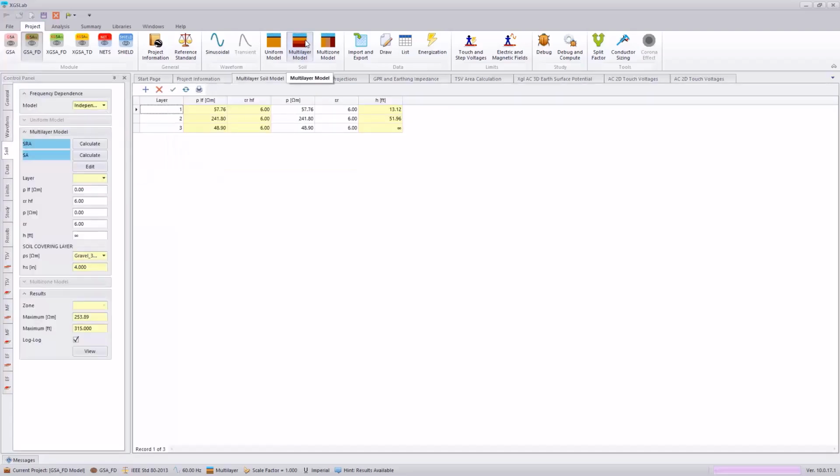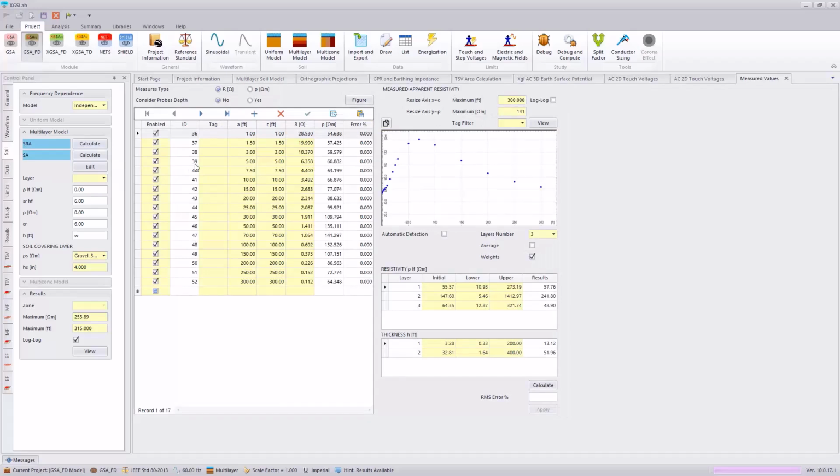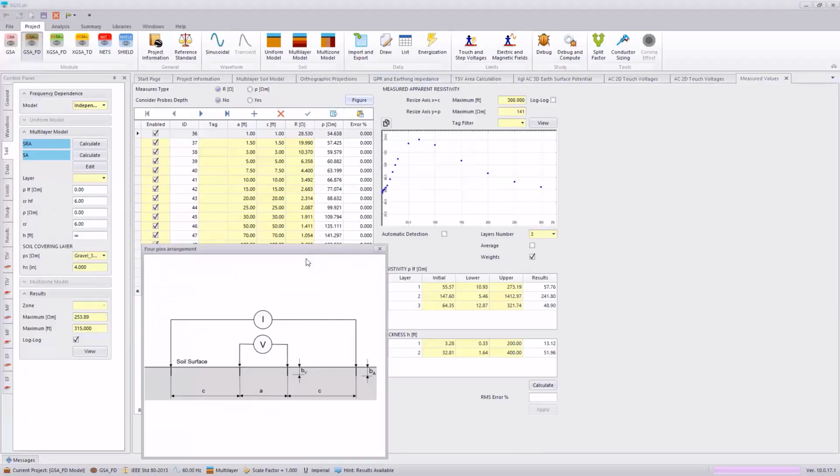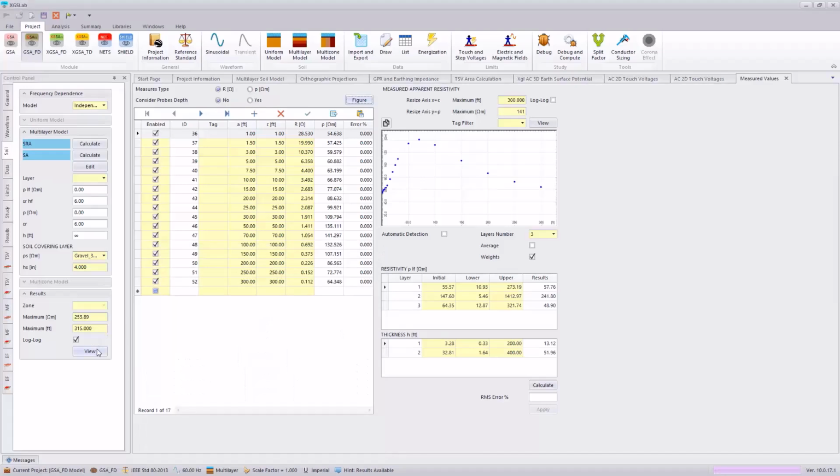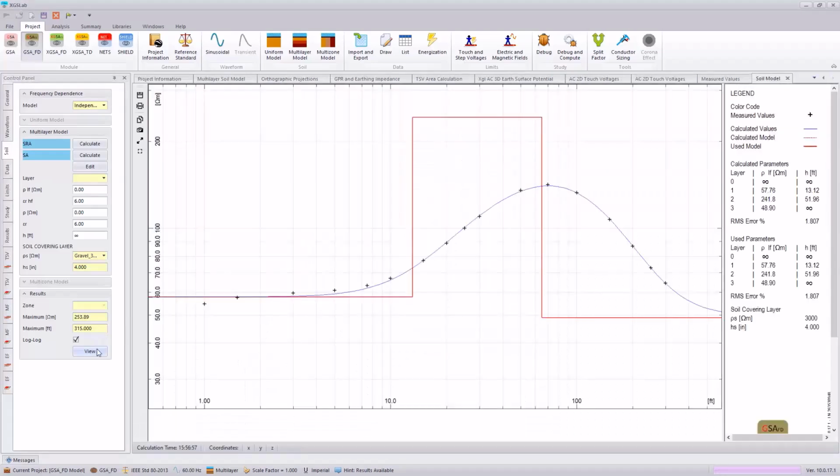Next, we want to evaluate our soil model. So we can take this multi-layer icon and this table to manually enter in soil resistivity or soil model, or we can generate a soil model based off of native soil resistivity measurements using either the Wenner or the Schlumberger methods following the spacings provided below. Using this method, you can generate a soil model and capture this graphic for reporting.